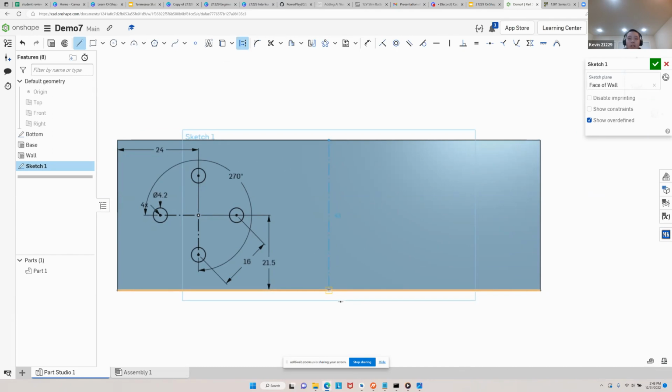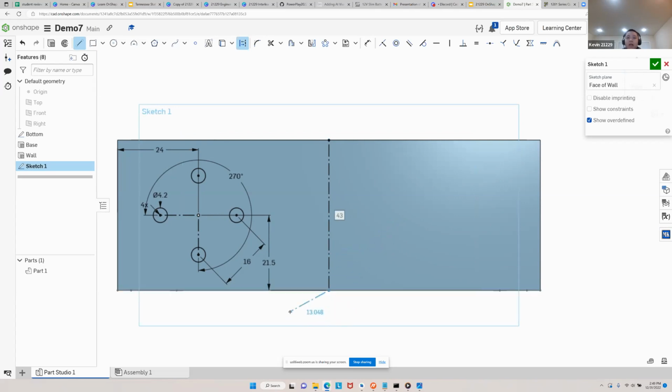And once again, I see that yellow square, so I know that this line I'm creating has its endpoints at the midpoint of the sides of the battery box. Then notice that Onshape lets me create a new line when I'm dragging around the second endpoint. I don't want to, so I am going to press the escape key to escape this tool.